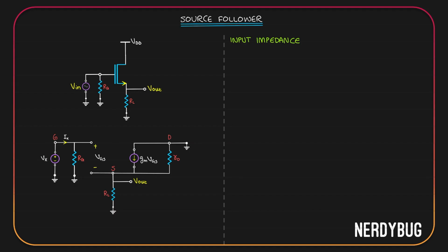This is pretty simple because obviously since the circuit is open over here, no current will flow through this. All of Ix has to flow through Rg, and Vx is connected across Rg. So Vx by Ix is going to be Rg, and that is our input impedance. Input impedance is whatever resistance we have at the gate.